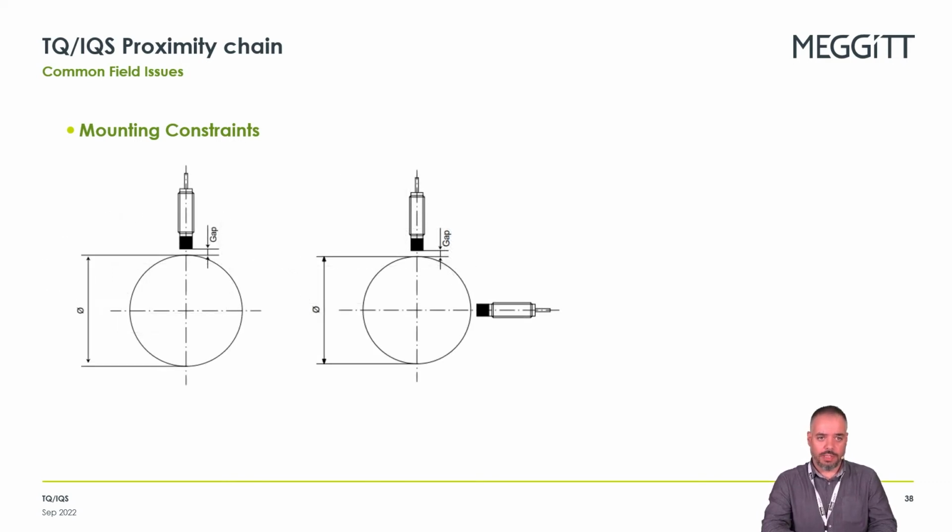For rotors, there is also a minimum diameter that must be respected, otherwise the measurement will have an error. If two sensors are used, then you will have crosstalk and you will end up with additional noise in the output if the diameter is below a certain value. You can find this information also in the installation manual.